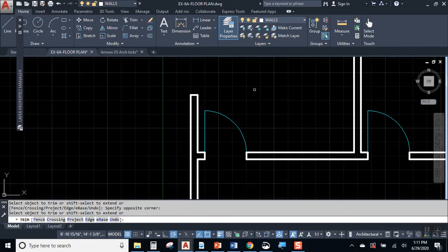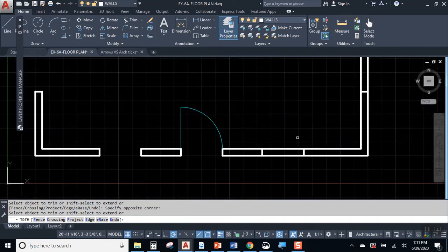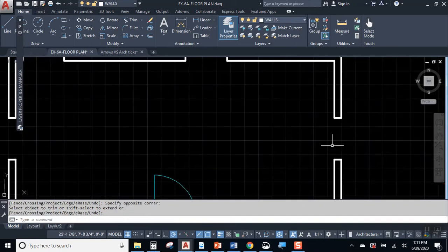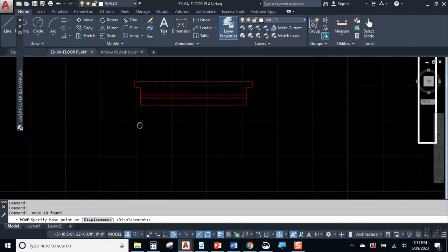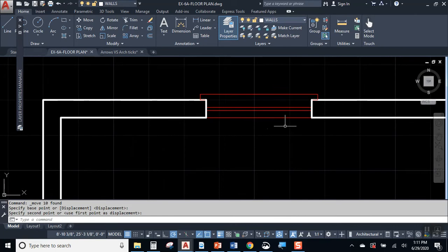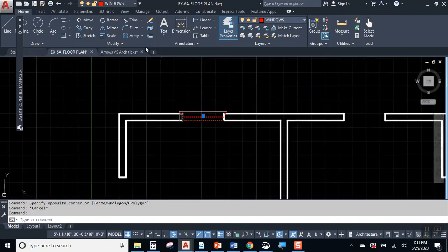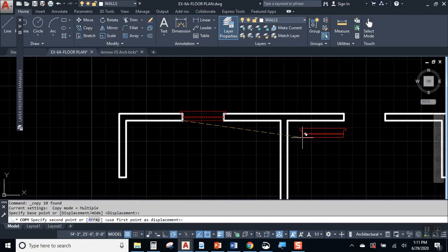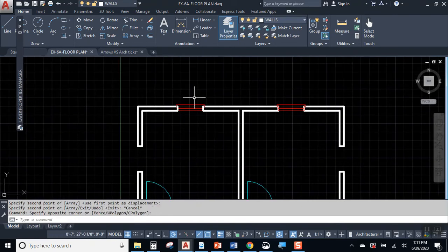All right. So we erase the openings where the windows are going to go. And then we'll take our group and we will move it into position. So we move it so that the inside corner is down here. And then if you wanted to, you can just go around and copy, copy, copy. Right. And you can even use mirror once you get your top ones done.